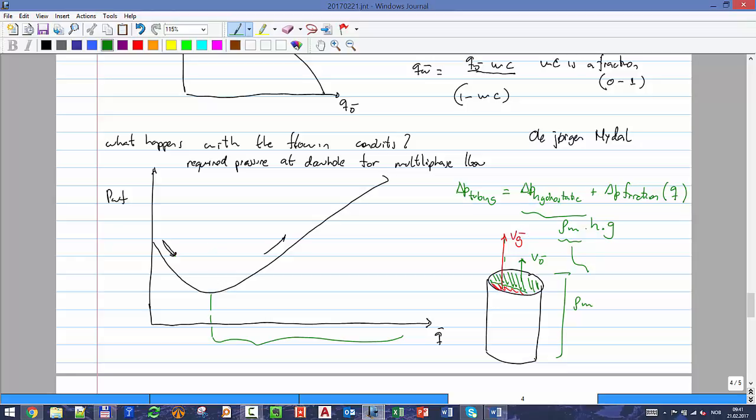What I'm saying here is that when I'm increasing the speed, the gas first, in this part of the area, doesn't drag the oil. If you put them separately, if you take just the oil, you will have some shear stress caused by the gas. Remember, the gas is going higher, so it causes some force to pull the oil up at the interface. But at very low rates, that's not enough to lift it. So the oil will take a very large area, because it's moving very, very slowly. Remember that.